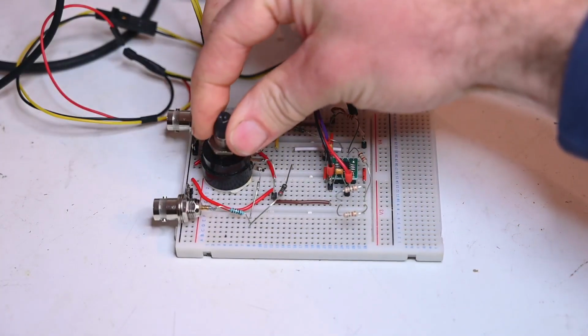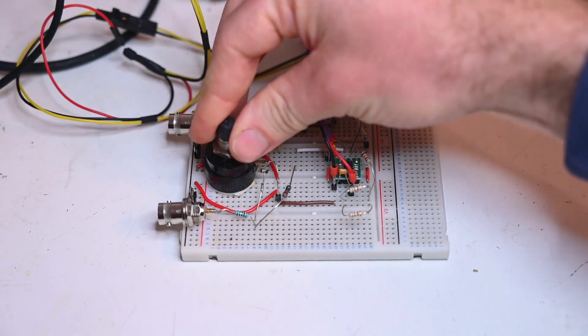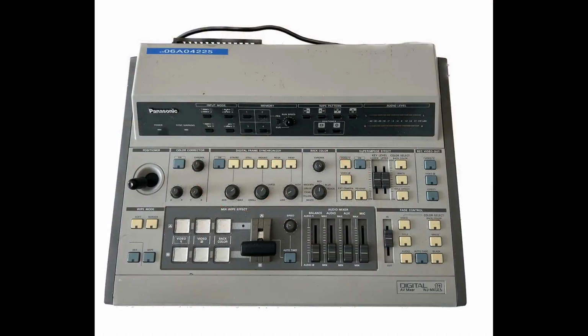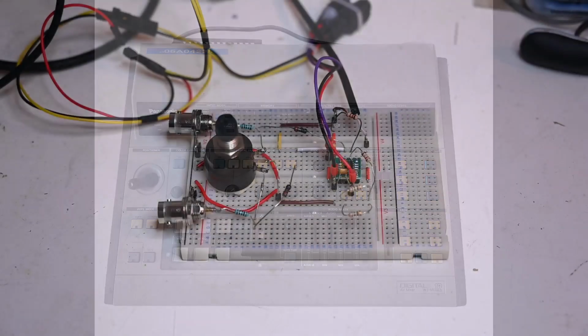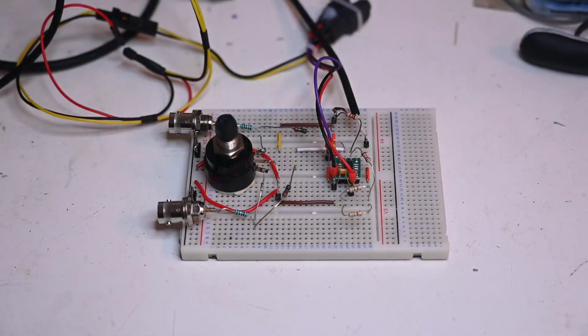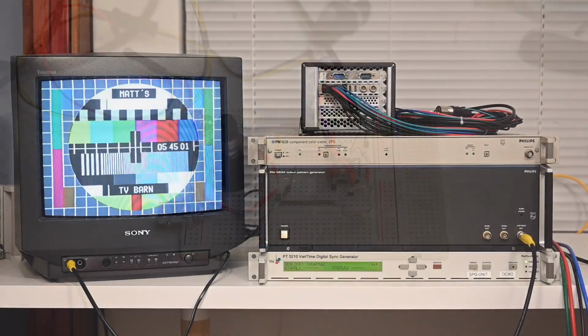Now you can get small mixers which are designed for unsynchronized signals. Now these are for hobbyist use. What they do is they take the analog signals in, digitize them, mix them digitally, and then convert back to analog again, which is a very complicated device, but doesn't require any skill to operate. Whereas mixing video signals with a purely analog device like this one is actually quite difficult, and this is really what we want to talk about in today's video.